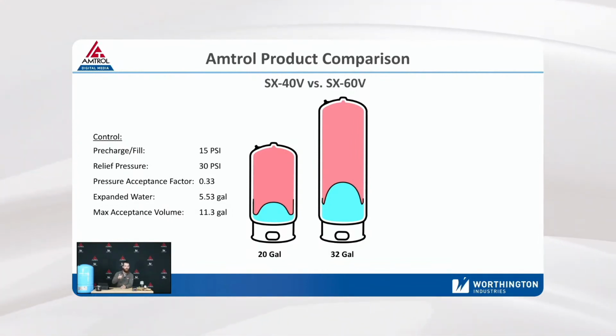And again, it's going to be important as we go forward. And that's why we ask about pressure ranges too, if you're curious on all those sizing charts, is because that's how we know what our acceptance factor is going to be.